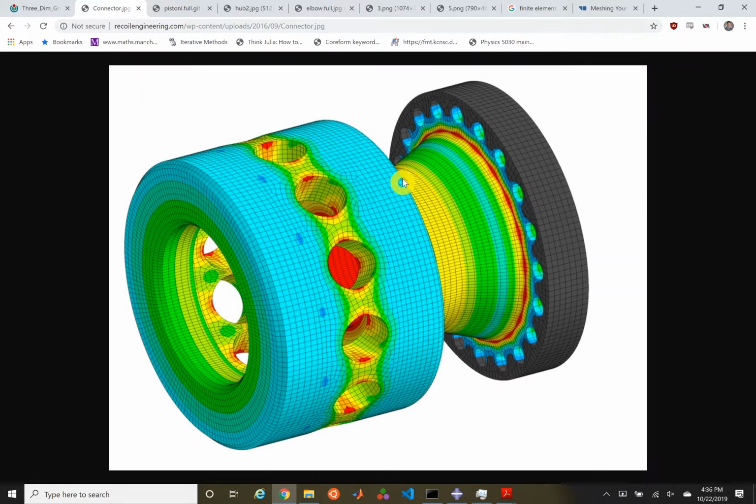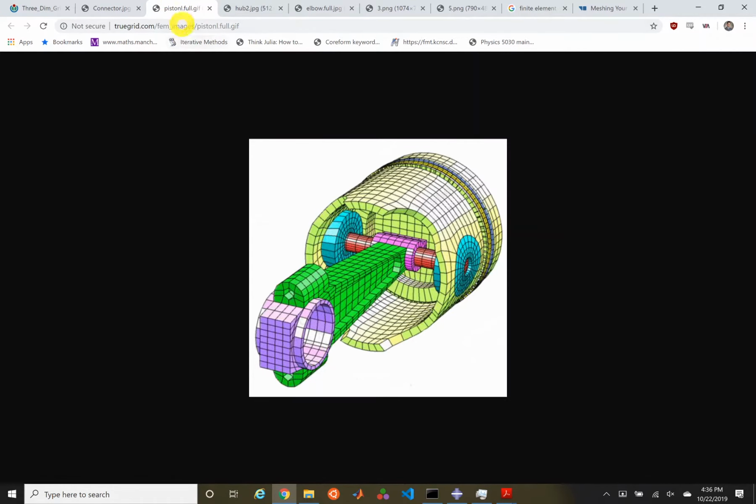But also just that this is a fairly well done hexahedral mesh. And there's not a lot of degrees of freedom that are required for this mesh because it's able to be a linear hexahedral mesh as opposed to a degree 2 quadrilateral mesh. We'll also talk a little bit about meshing of assemblies. And so this is an example of a piston that's been meshed. So multiple different parts of this assembly have all been meshed to match up to each other.